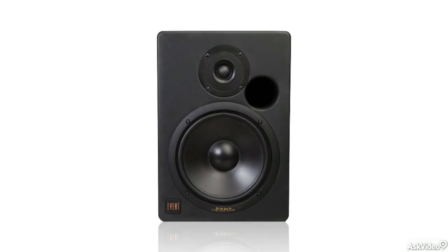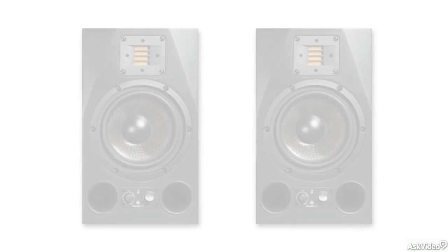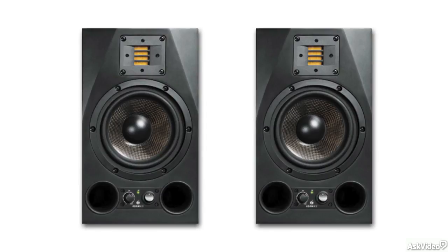Dynamic moving coil designs are used in the vast majority of speakers intended for use in professional audio applications. But ribbon elements and electrostatic elements are also sometimes employed, most commonly for tweeters. Just as with their counterparts in microphone design, ribbon mics and condenser mics respectively, these designs may provide a somewhat clearer, more delicate high-frequency response. The most typical approach is to combine, say, a ribbon tweeter with a standard dynamic moving coil woofer. For example, the speaker company Adam offers a very popular range of studio monitors that incorporate ribbon tweeters.